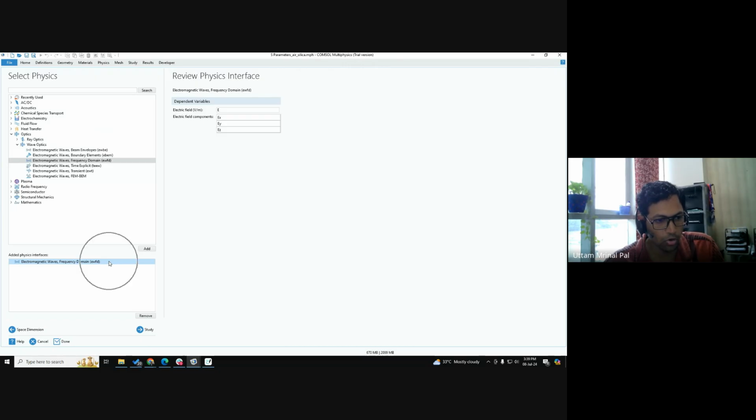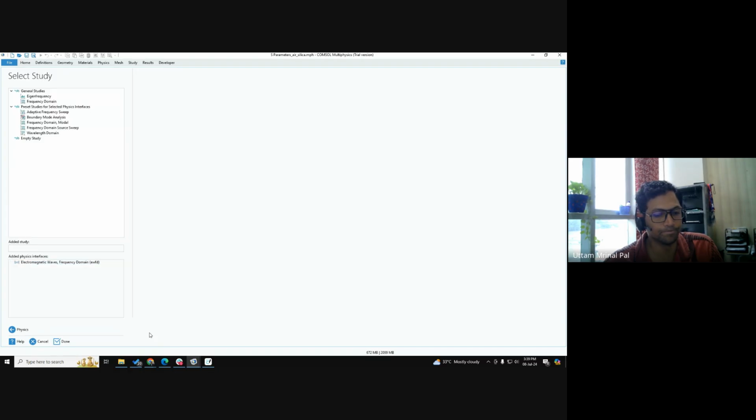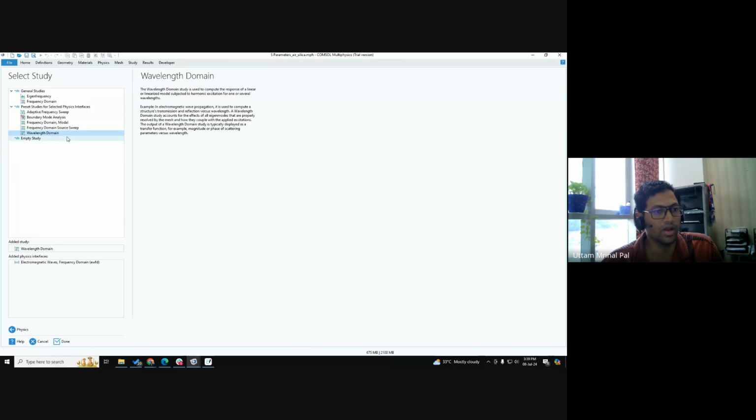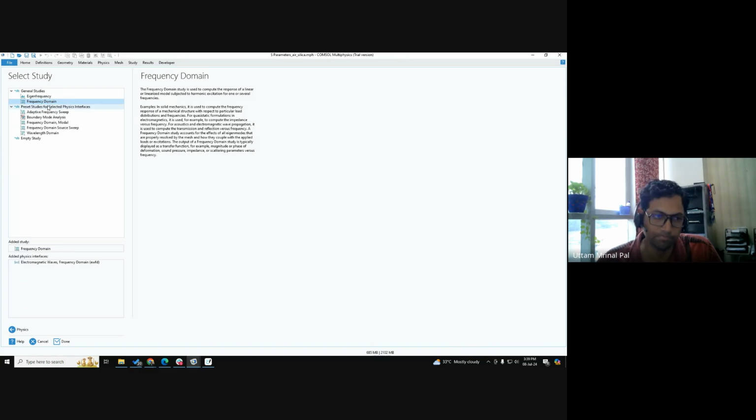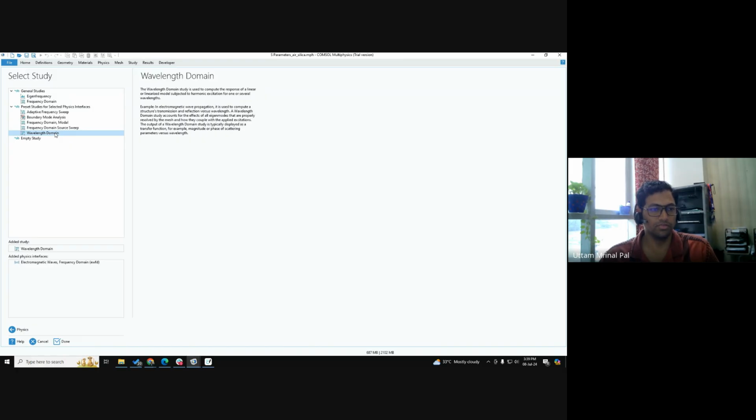I hope you have added electromagnetic waves, frequency domain, and then click on study. There are many different kinds of studies. You can use either frequency domain or wavelength domain. Frequency domain is the most used study, but if you want to use wavelength domain, it's the same study and doesn't change anything.